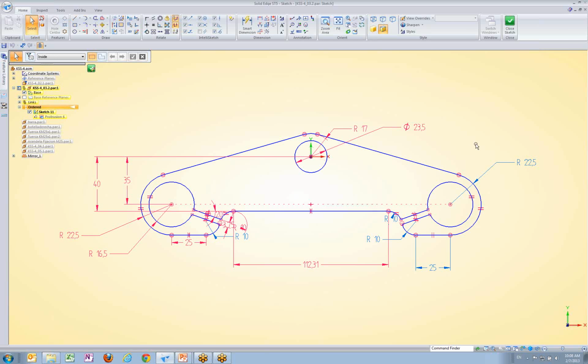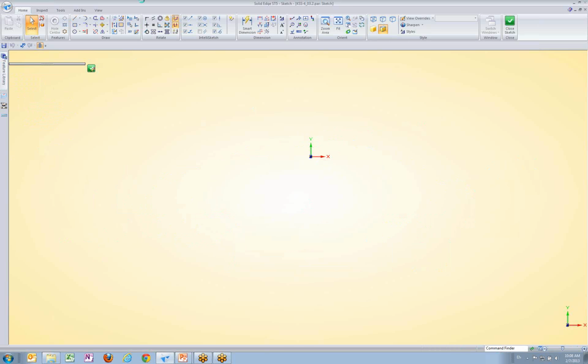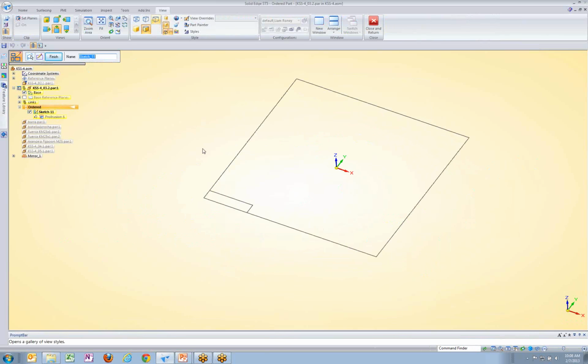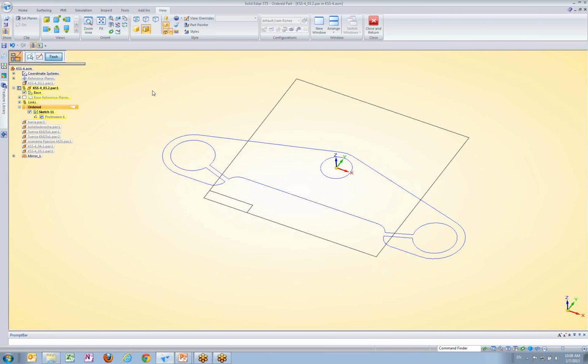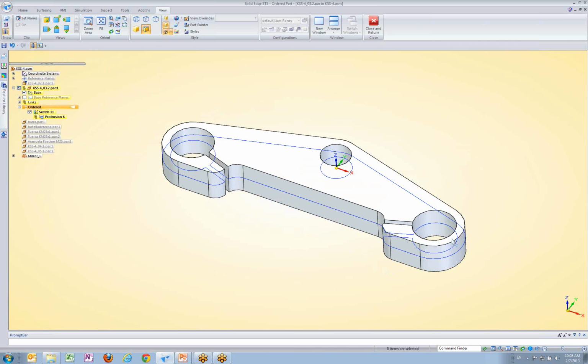So we see here there's a lot going on, and it may be difficult down the road to modify everything at once from this single sketch. So that's why we have these best practices, where you break things up into simple features. The downside of that, of course, is that I'm making concessions for my modeling tool as opposed to capturing my design. So that's a big limitation in history-based modeling.